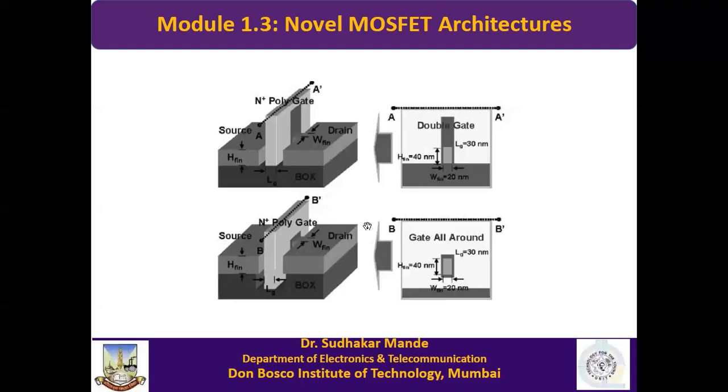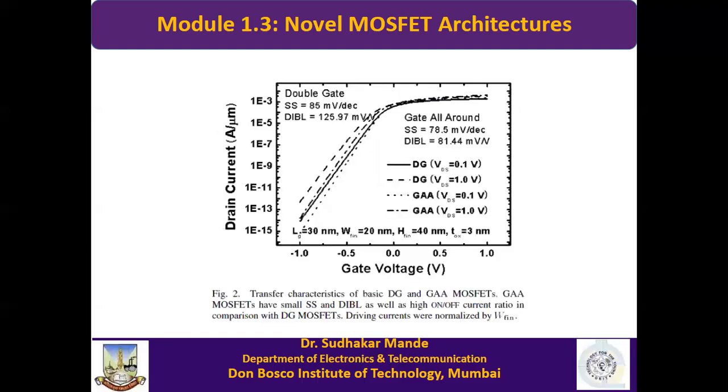Right. So what are the advantages of this one? Because the working principle is the same, whether it is a CNT FET or a MOSFET. When you apply some electric field to the gate, electrons from the source will enter into the channel, and there is a drain field. That drain field will collect those electrons, or in general we can say that the drain will collect the charged particles, and thus when we apply gate voltage, the MOSFET is turned on.